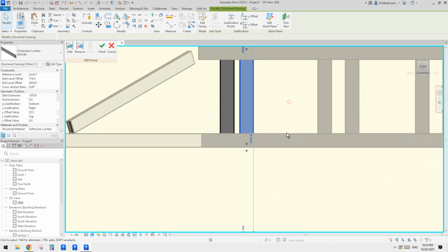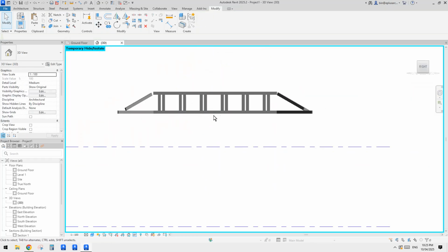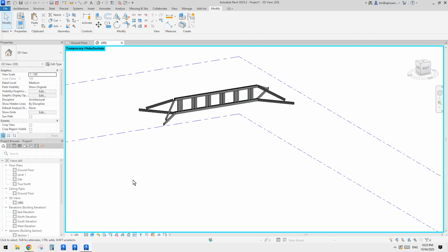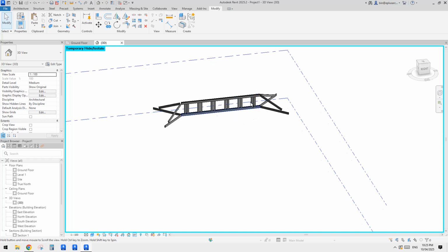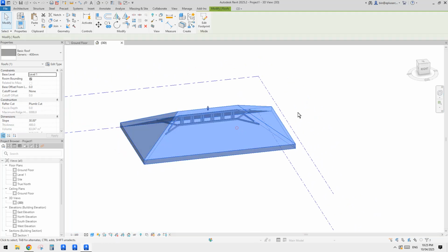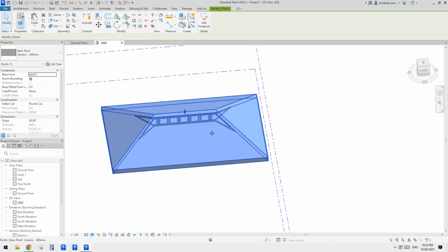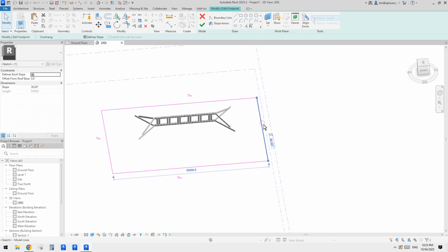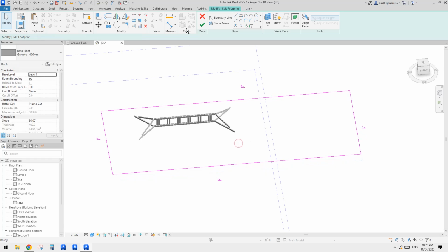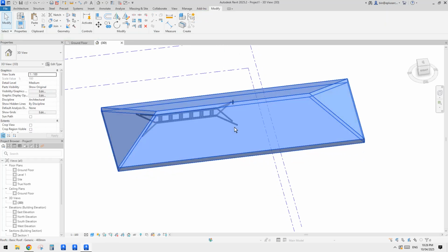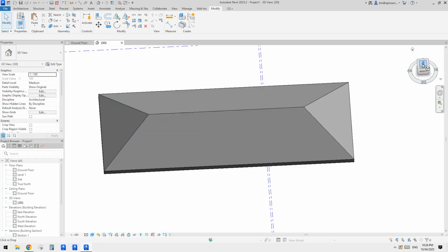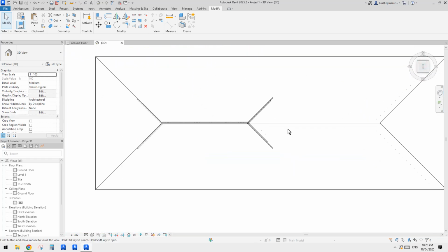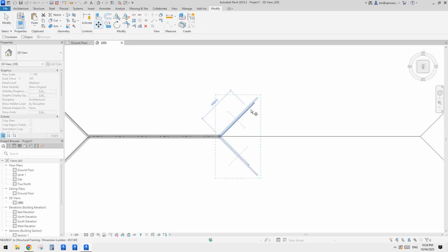See here. Hang on, maybe we should move this a little bit closer. Maybe, yeah. Oh, looks like the roof is not long enough. Relative to this one, it's quite long and skinny. Mine is not. Maybe let's just adjust the roof. I'll make this a little bit longer. So maybe 24 meters instead, right? That should be long enough. HH. Now we can just move. Oh, maybe I'll type HR, go to top, wireframe WF, or just directly move this.